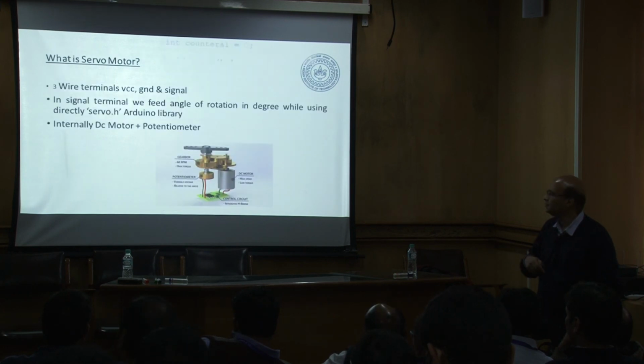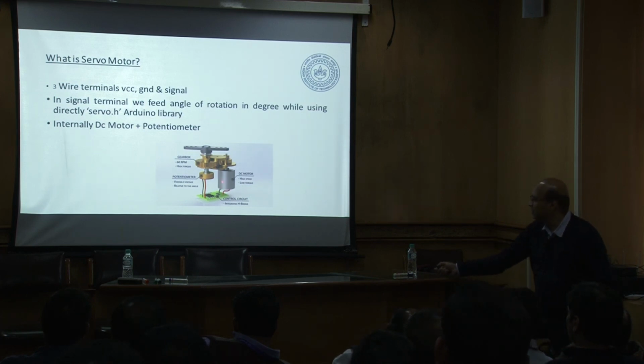position of a motor, we talked about these motors, which are very, very common now. How do you control this motor? There is already a motor, a potentiometer, and a gearbox inside. So we connect the link of the robot onto this linkage. And there is a PID controller inside, which is pre-calibrated. So what it basically means is that when I give the PWM signal, the output link can rotate from 0 degrees to 180 degrees.